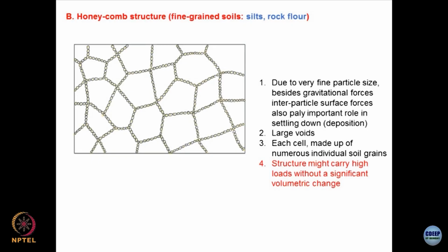These types of structures are very good as far as the load bearing is concerned. We were talking about the foundations in the very first lecture, clear. So, if I do investigation, if I take out samples, put the sample beneath the microscope, and see it the way I showed you last time, and if I can establish that this is a honeycomb structure, I should not be very bothered, because this type of structure acts as a reinforcement. So, the load bearing is very good, and hence the volumetric deformations are not going to be much.